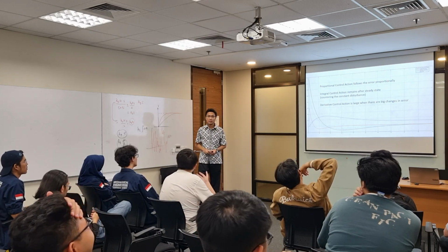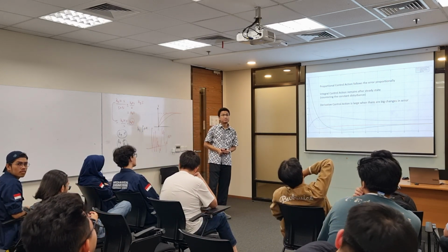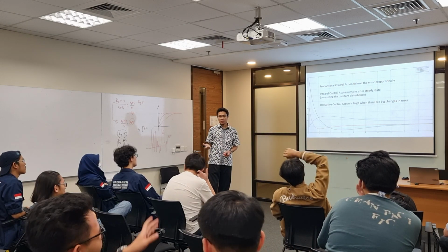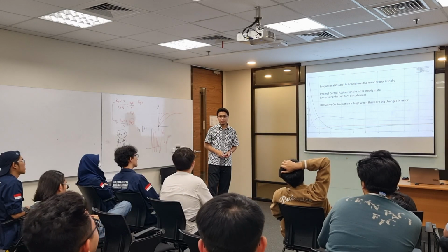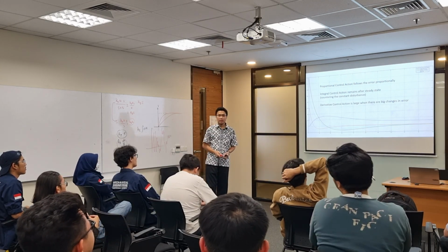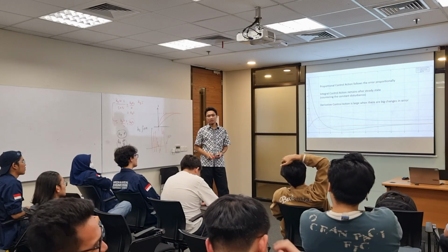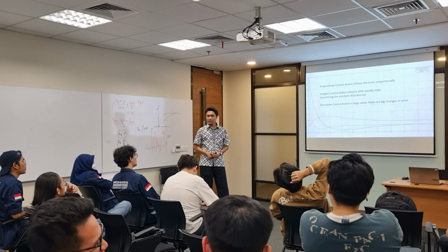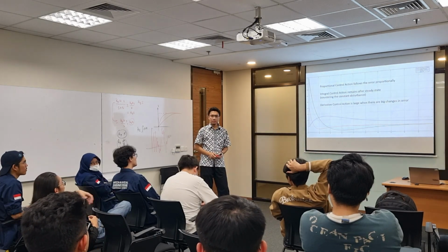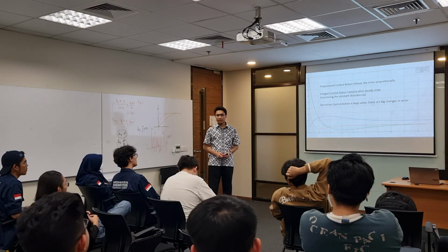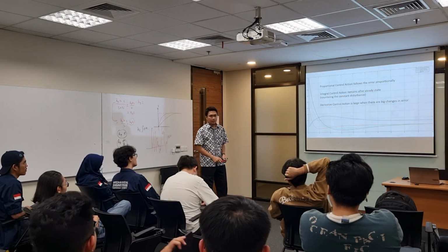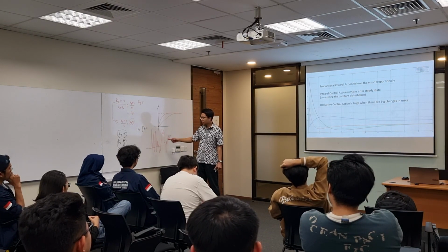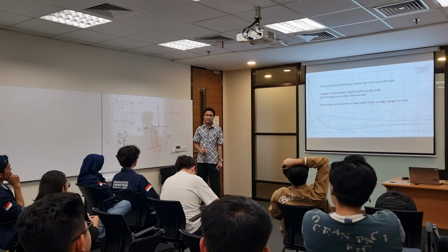So we can say that integral control forces our system to reach the steady state value. It will make your response slower, correct? The integral control slows down your response, but it ensures steady state value achievement. In this kind of case, you don't want accuracy. You just want a fast response.